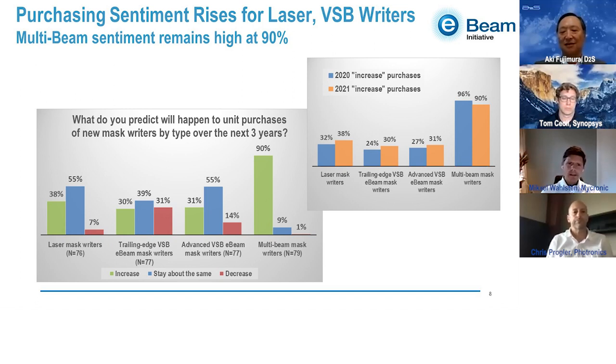And just alluding a little bit to what you can produce on these writers: the I-line you can probably push down to 130 nanometer and the DUV around 90 nanometer. But that being said, we will also have a quite ambitious roadmap around these machines. For the future, we have the ambition to push this, I think, one node forward at least, both for the I-line and DUV.